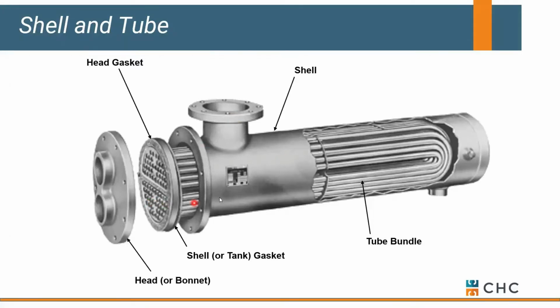We certainly have water flowing through the tubes. So we come in down low with cold water, and we leave nearest the source with warmer water, and we send that out to our system. But if you look at what's happening on the shell side, you'll notice we have a very big connection on the top of the shell, and a very small connection at the bottom of the shell. So this particular unit is actually a steam to water setup.